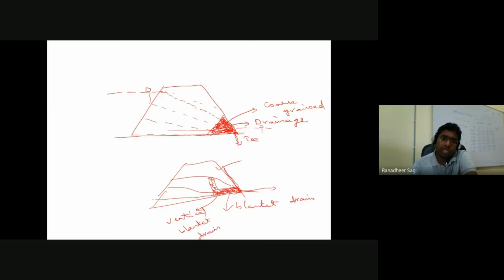Depending on your requirement, we have different types of drains and different mechanisms of providing them. Now, what is the material that you are going to provide here? Are we constructing some separate structure inside the earthen embankment? It's not that we are constructing a particular structure. Rather, in that region, instead of using the same fine grained soil used in constructing the embankment, we place a coarse grained material, or maybe some geosynthetic materials, so that the water flowing through the earthen embankment can easily pass through the path you have provided for proper drainage.